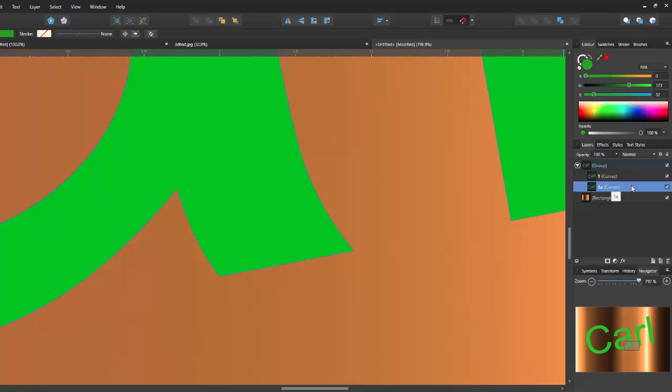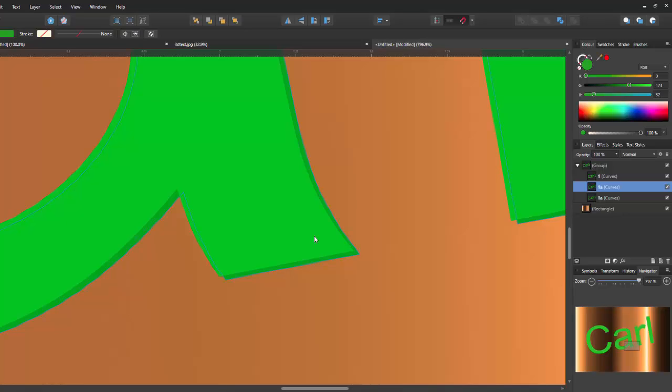So yes, I'm still highlighting this layer, and what we're going to do now is what I think is called power copying. If you hold down the control key, and I think that's the command key on the Mac, and then left click and just drag out very slightly. I'm going to come down a little bit and to the right a little bit, and then let go of the command key, control and the left mouse button. You can zoom out if you want now.